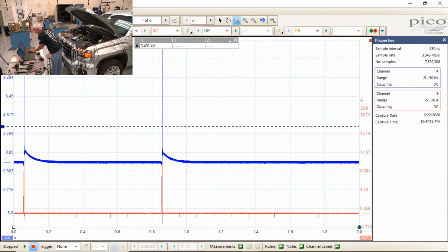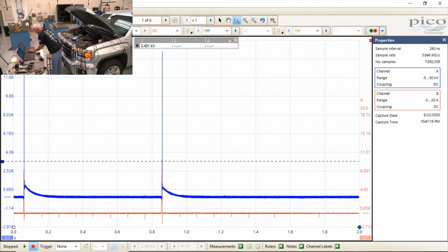But look at there, the kV cranking, 14,000. So at idle, the running compression is probably 60, 70 PSI. And then at cranking, my cranking compression is probably 180. And you can see my cranking compression required almost 15,000 volts, and my running compression only required 3,500 volts. So compression makes a big factor on how much kV it takes to fire a plug. Wonder if you knew that.